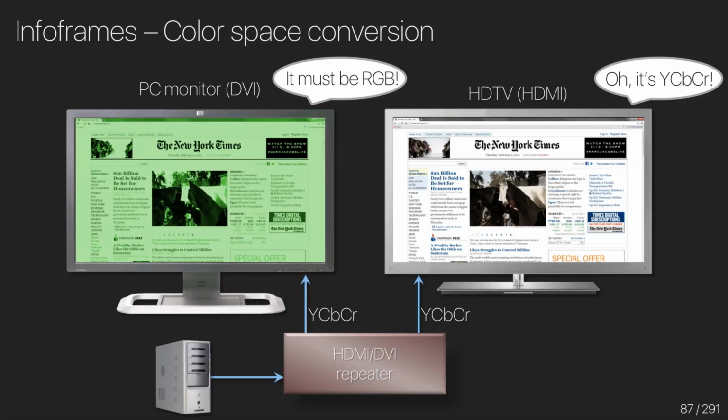What you could do to resolve this is edit the EDID being presented to the source device and disable YCbCr support for it, because everything's backwards compatible with DVI and RGB, you would be able to get it to send an RGB version of this signal.